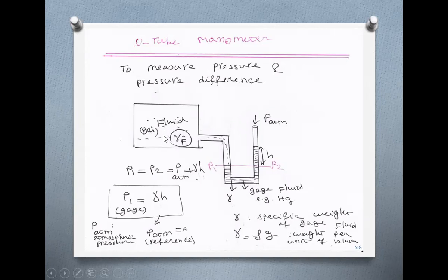You know why? Because for gas with low density, maybe if you're talking about 100 feet, that makes a pressure difference. You go up and down, and it's 100 feet or 10 feet, but not for such a small distance. Pressure here doesn't differ much from pressure here. But if it was liquid, it does matter. So you say pressure here is P1 plus gamma H, and so it would be different. But for gas, doesn't matter.